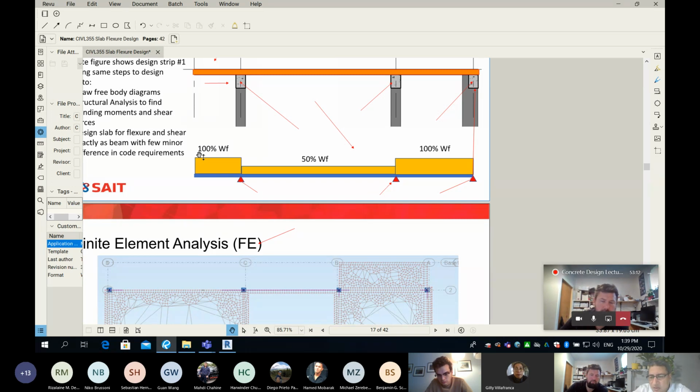You can find the bending moment that is acting on your slab, because simply the slab looks like a continuous two-span with one overhang to the left. Are you guys following? I know you guys cannot do that by hand. You were never taught how to solve indeterminate structures by hand. But if you use SAFI, same as we did earlier in this class, you should be able to find the bending moment affecting your design strip.